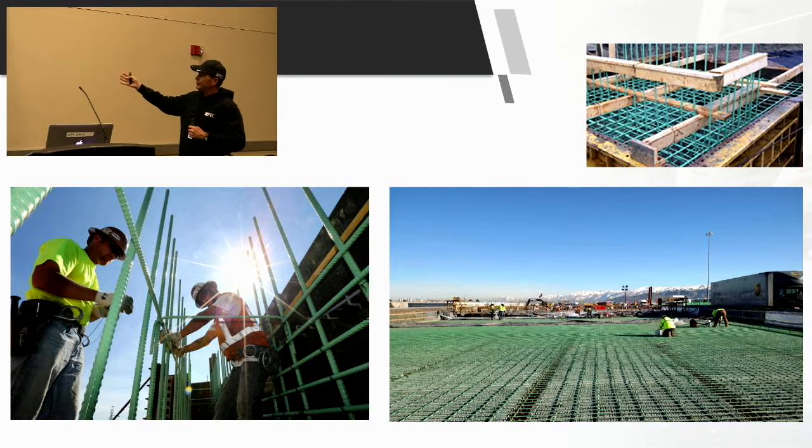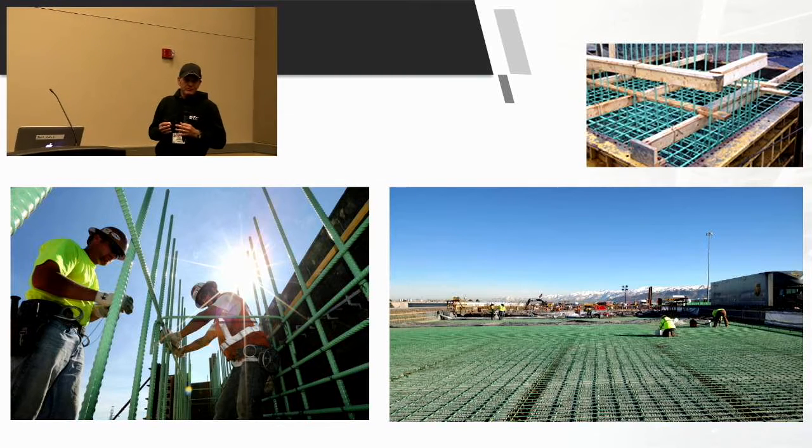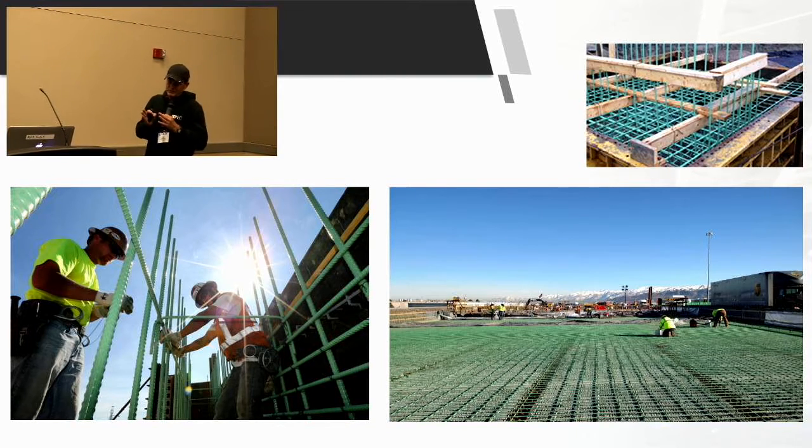So I'll go out and do a real quick visual, looking at all the bars, walk the whole thing, look at ties to make sure they're 100% tied. If in any one direction it's over 9 inches, it's 100%. If it's less than that in both directions, they can do 50%. You've got to remember, if it's 6 inches one way and 10 or 11 inches the other way, it's 100%. They don't like hearing that because it's just more work for them.